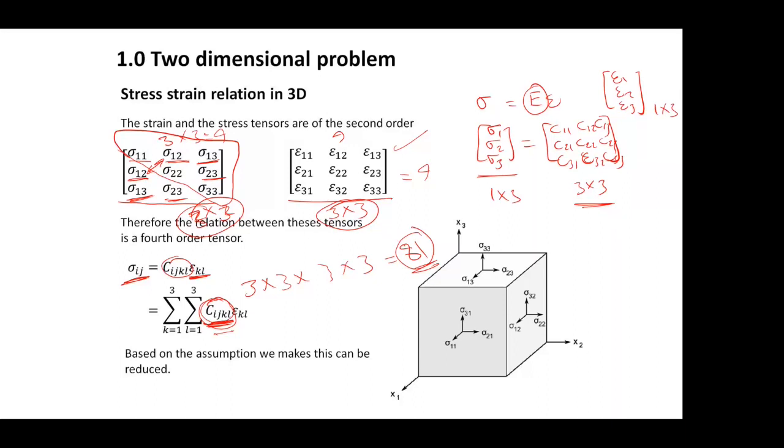Tell me, or probably any one of you could tell me, how many actually independent components do you have in the C_ijkl? How many independent components actually you have used in the past? Anyone can tell me? So in the most general case, we're talking 81 independent components. Now, how many components you have used in the past? In the 3-dimensional case, think in 3 dimensions.